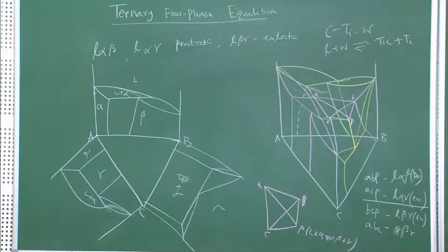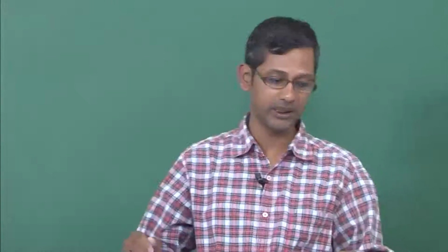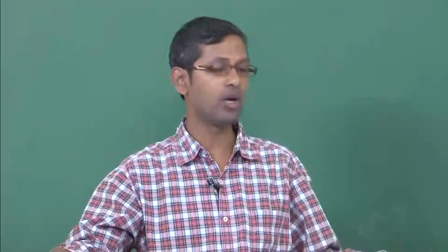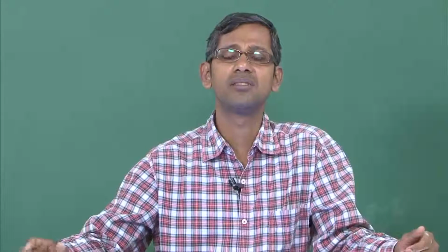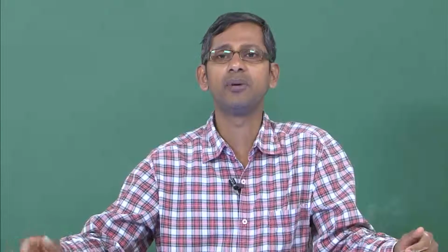So, that is actually quite a small description of this ternary quasi-peritectic reaction, and in metallic systems this has been observed prior to any eutectic or peritectic reactions.